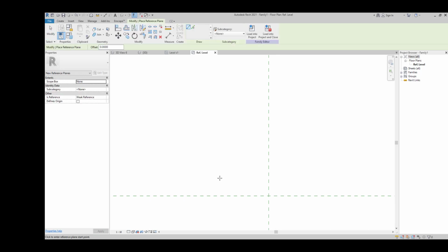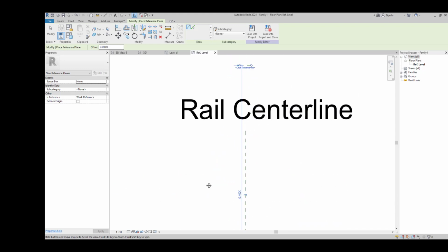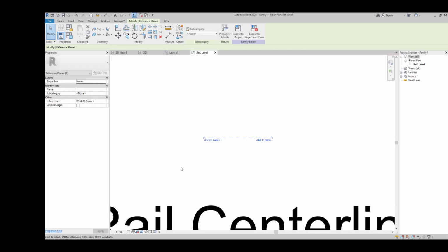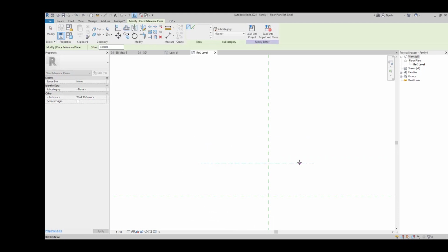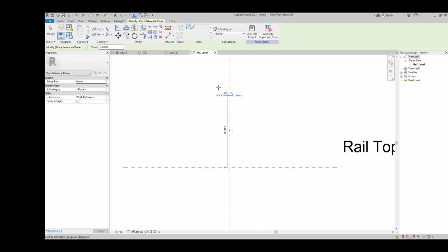So we can go to the reference line, we can draft our reference line and change the direction here to 40, so it's going to be almost here. If we want to design our profile by 40, we need to change it to 20. Each side is going to be about 40, so I'm going to use reference plane again, change it to 20 centimeters, and it's going to be here.